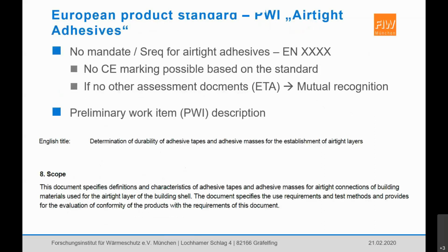Okay, so some last four slides about the current state of the European product standard. First, worth remarking that we have no mandate or standardization request for the airtight adhesive, so it will be a normal European standard, not a harmonized standard. This means, of course, that no CE marking will be possible based on this standard, as CE marking requires a harmonized technical specification. This can be a harmonized standard or a European technical approval.